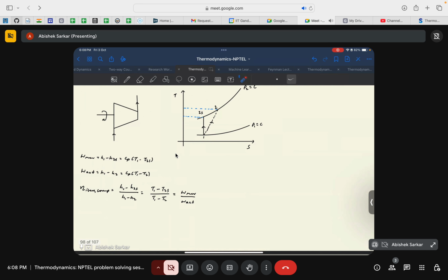Okay. In general, if it is done through a constant pressure process, then this relation is valid, but in general, this relation is not valid for water. Okay, but still, in that case as well, if you consider water as the working fluid, then you will see similar curves. But in that sense, the relation would be modified. It will basically be the integral of Cp dT, but the very concept of the increase in the work input because of the irreversibilities in the thermodynamic process would still remain in the case of water as well. Okay, that's what I wanted to show.